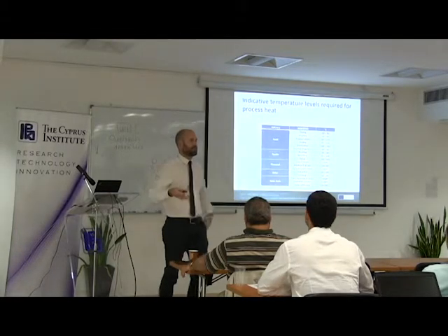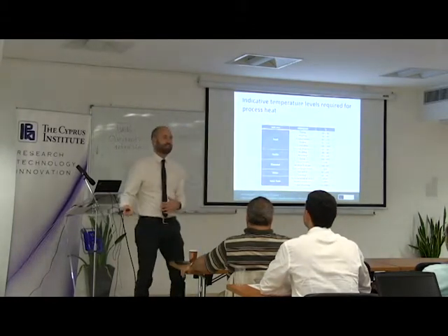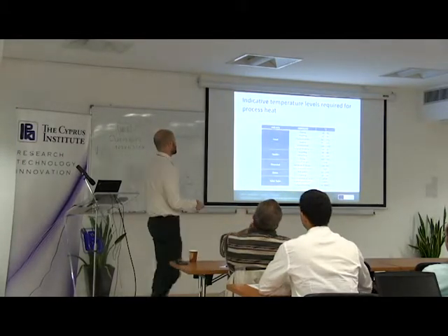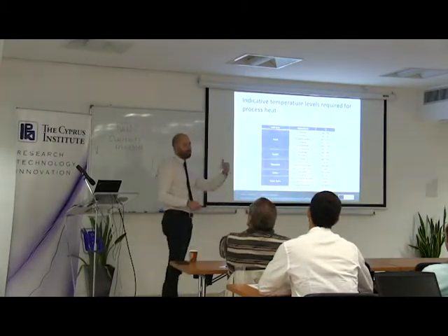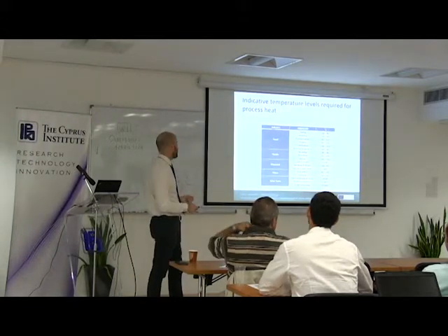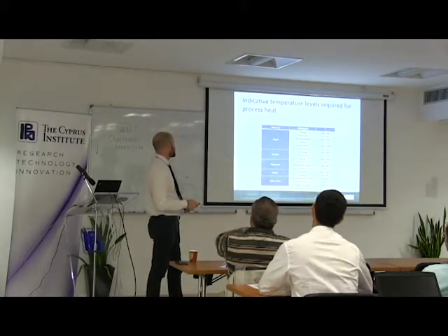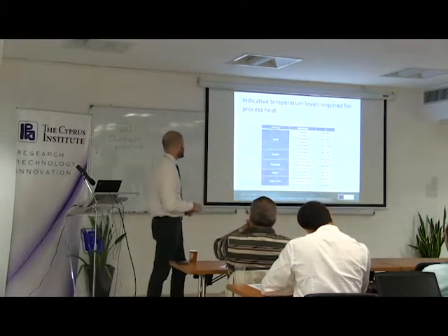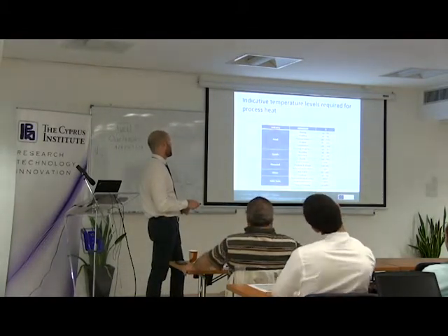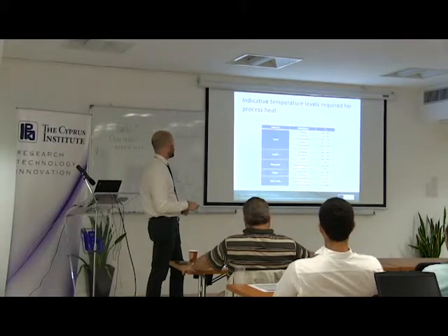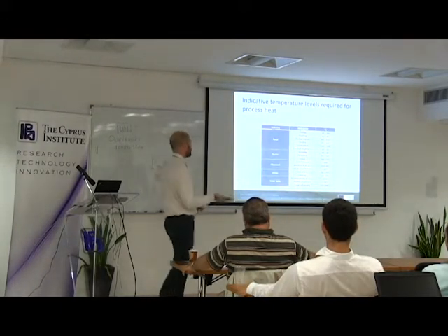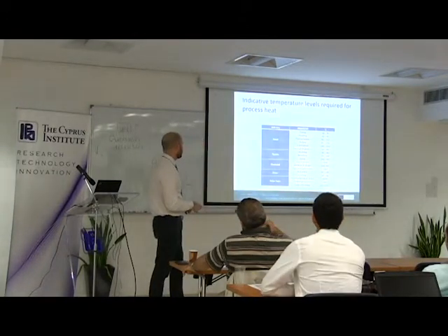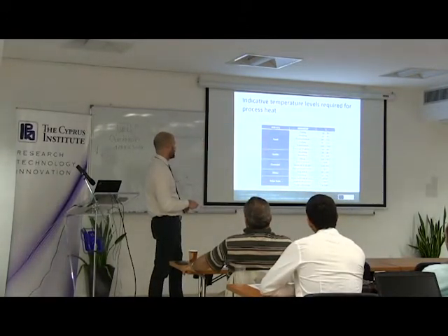The chemical industry is mostly about producing a process or service stream for the plant. You usually have 3 levels of pressure, which correspond to 3 levels of temperature. We go from low pressure steam, below 140 Celsius degrees, medium pressure steam from 140 to 205, and high pressure steam about 205. Then hot water and cooling, and finally also solar fuels.